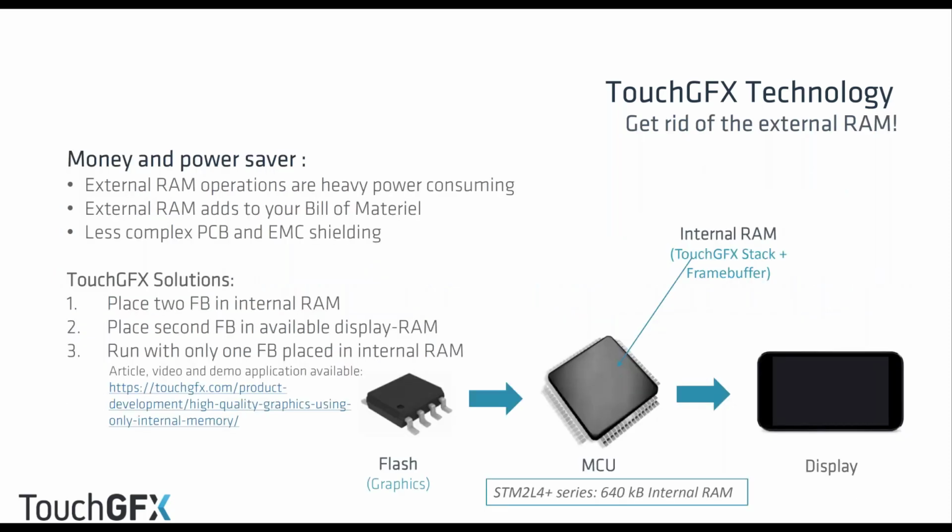And this is something that we see a big push in the market, primarily for the high volume products, actually needing applications without external RAM, saving cost as well as saving power consumption. And our solution from TouchGFX is, first of all, if you have available RAM in internal RAM, place 2 frame buffers in internal RAM, and you will have a really smooth and great running application. The second option is to utilize RAM in the display. Here you can place the 2nd frame buffer, and again have a really good setup.